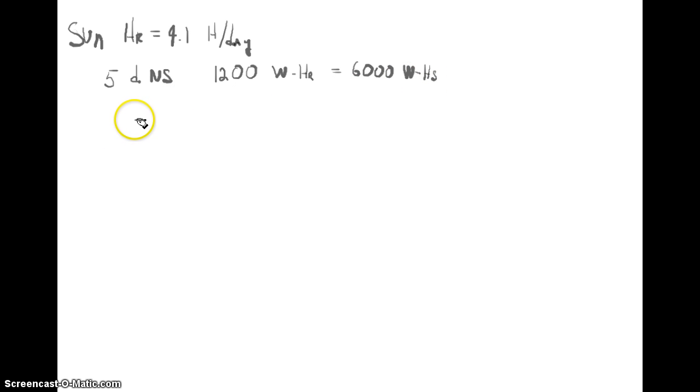All right, so we start out, we know we need 6,000 watt hours in our battery to run this for 5 days with no sun. But also we know that batteries are not 100% efficient. We know that sometimes some of the energy as we try to stuff this thing in is going to escape in heat. So we tentatively think about batteries as 90% efficient. Right? So we're going to derate that battery by 10%. That turns out that we now need a battery of 6,666 watt hours. All right?